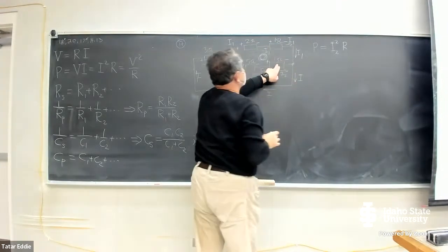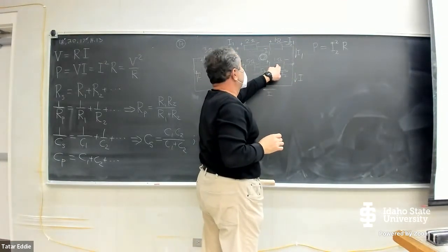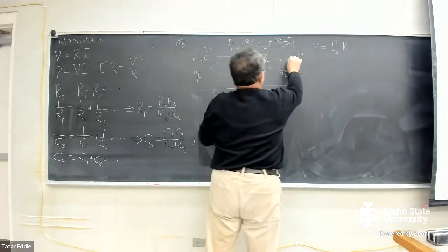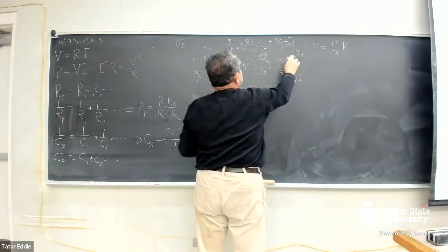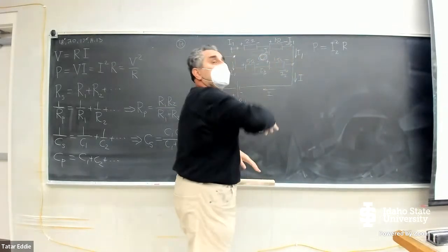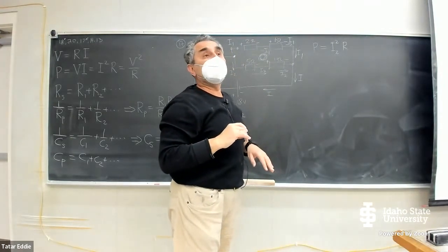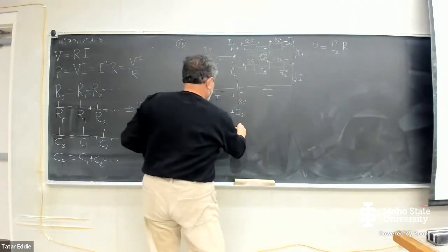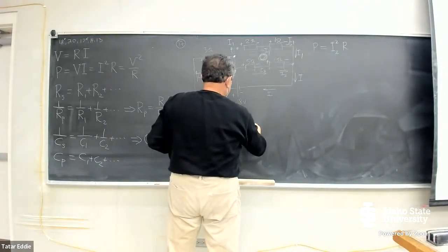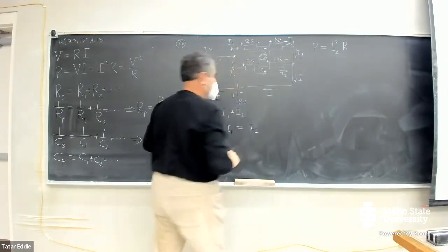Again, I encounter a 1 ohm resistor. But now, since I'm going clockwise, I go from minus to plus. This is a potential rise, and it has to go to the other side of the equation. In other words, I'll write it as 1 ohm multiplied by the current there, which is I2.